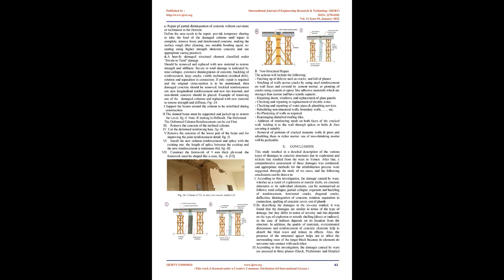When cast-in-place concrete or shotcrete is to be used, the existing concrete surface should be prepared to ensure sound bond between old concrete and new concrete. First, all unsound, damaged, or deteriorated concrete should be chipped away by mechanical means. The second step is to rinse the surface, clean it and roughen it by sandblasting, and then rinse it again.